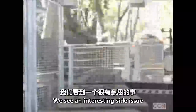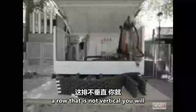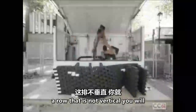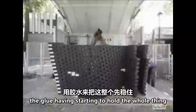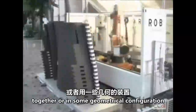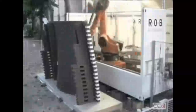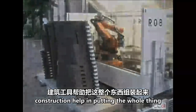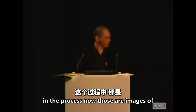Here you see an interesting side issue. If you produce a wall that is not vertical, again it's about the process, you will have moments, for example, before the glue starts to hold the whole thing together, or in some geometrical configuration when the upper part is not in place giving counterweight, where you will need construction helping to hold together the whole thing. There we just used bricks that were not glued, that afterwards could be reintegrated in the process.